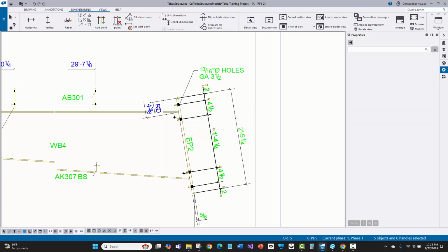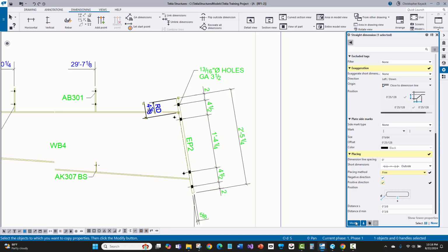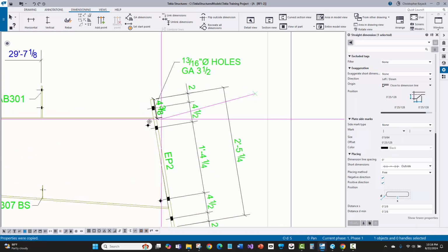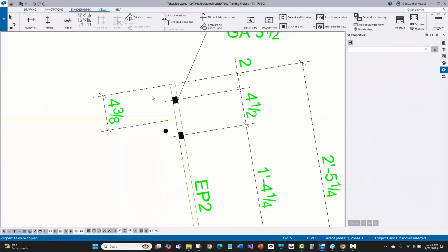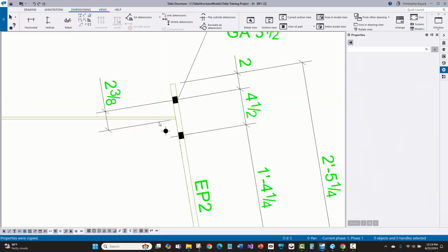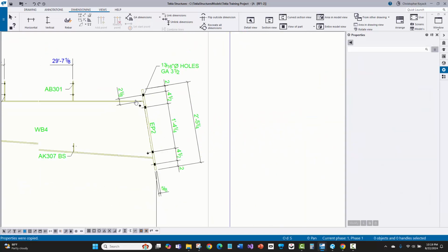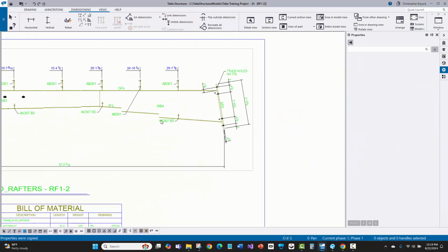Now the other thing too is I'm going to match the properties. I don't really want a running dimension there, so I'll use the paintbrush, select on that, modify, and there we go. And so then we'll drag that there, and let's just fix this to go to the hole. And looks like I even picked that there. I think you usually want the dimension there. And there we go. Now we got that dimension, got that all set.